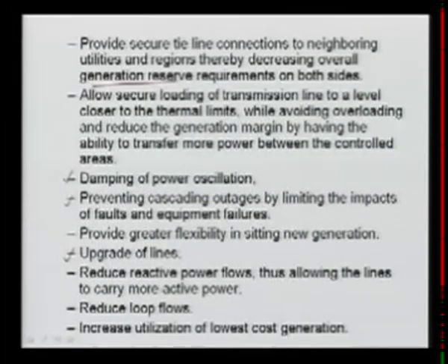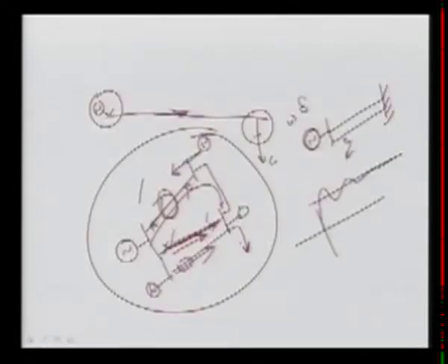so that we can go for more active power. What does happen? You can see, you are having a transmission line here between the two buses. This current which is flowing here is the magnitude, and here there is the I square R loss. So this line has some limitations. The real and reactive components are here, I is nothing but your IR plus jIQ. Here you can say real part and Q part.